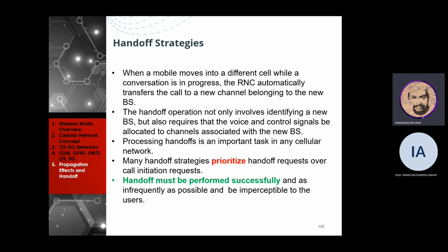So we need a handoff strategy when a mobile moves into a different cell while a conversation is in progress. The RNC automatically transfers the call to a new channel belonging to the new BS. The handoff operation not only involves identifying a new BS but also requires that the voice and control signals are allocated to channels associated with the new BS. So processing handoff is an important task in any